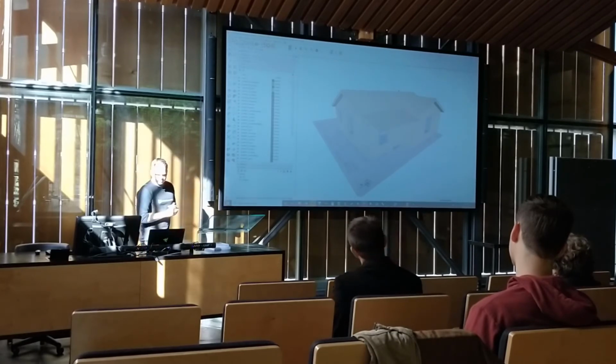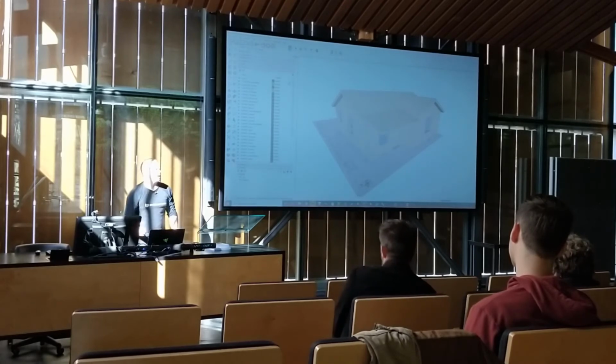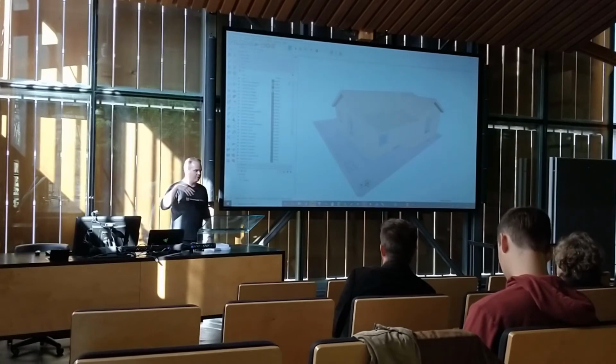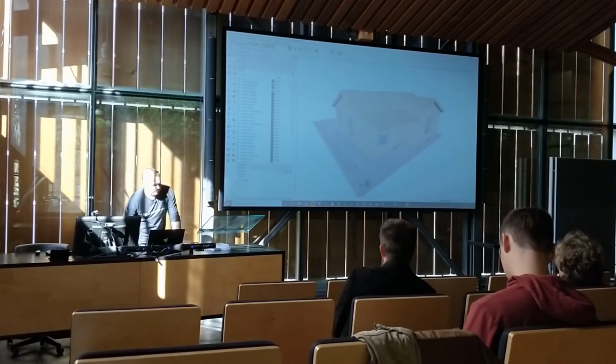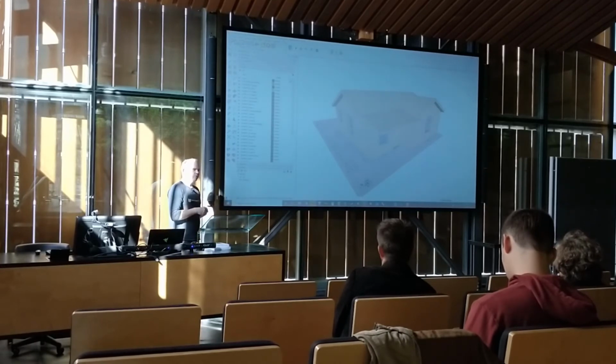With CAD, you're always using match properties, and you start drafting and then realize, I'm on the doors layer, I have to go back and fix this. You never remember to set the current layer. With this system, your current layer is always layer 0, and then you just go put things in the proper containers. Once you've assigned a layer, like level 1 doors, you don't have to assign it again. You just put the level 1 doors in that container right next to the other doors. It's a nice system in that way.